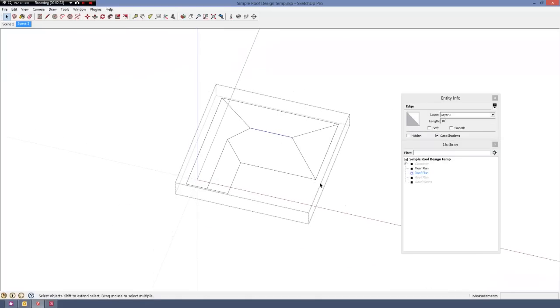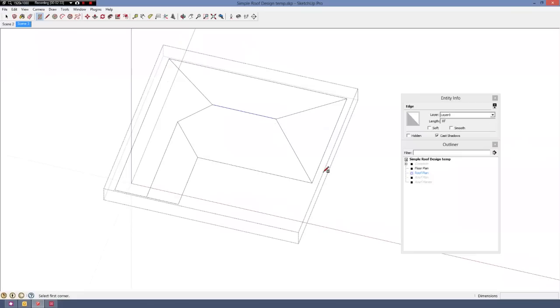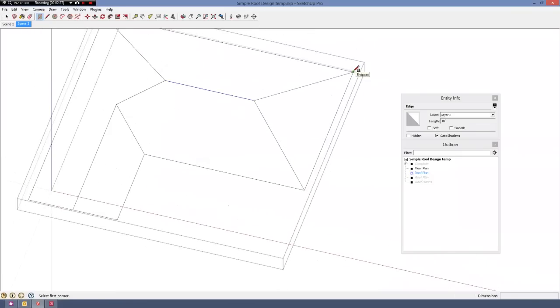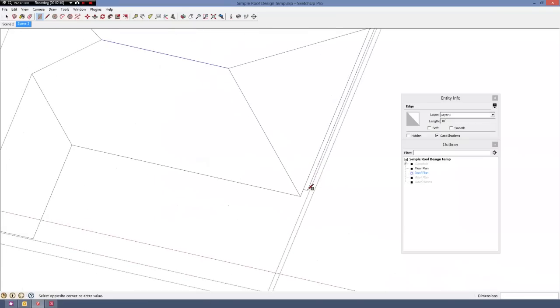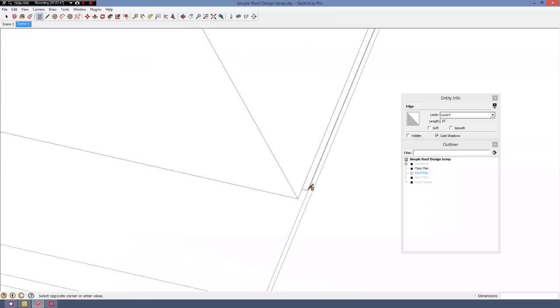Okay, to do that, let's go ahead and draw a couple of rectangles that are representative of our framing members. So we're going to need a rectangle that's 1.5 inches wide for our 2x, and then one that's 3.5 inches wide for our 4x. So along any straight line that's convenient, go ahead and draw a rectangle, drag it so that it's longer than any of the members that we wish it to represent. So I want to go ahead and accept this length. I think this length is good enough. On the lower right in the VCB you'll see 17 feet 5 inches, comma 3 inches. I'm going to press the tab key, then comma, and then type in 1.5 for 1.5 inches, and then enter. And the tab comma will accept the default length that I had dragged it to, and then the 1.5 defines the width.